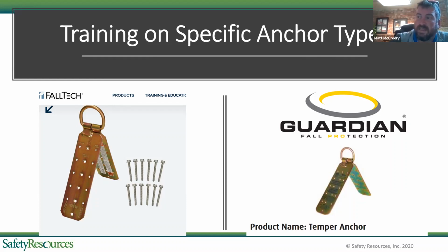My pet peeve is I see two screws on either side of a peak anchor. That drives me nuts because honestly, if I fall and I'm tied off to that, I could rip that out, and the anchor then just becomes a projectile after I hit the ground, to add insult to injury.